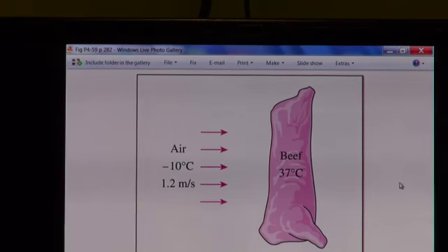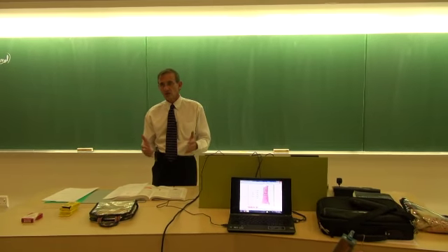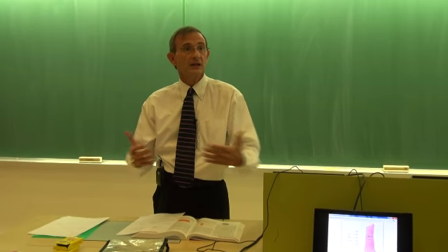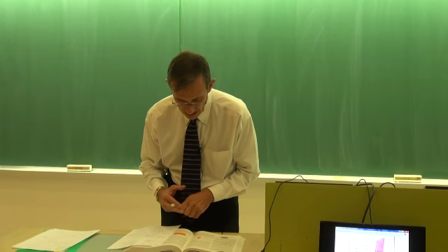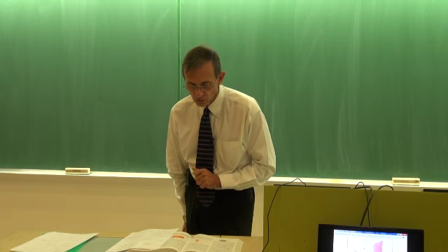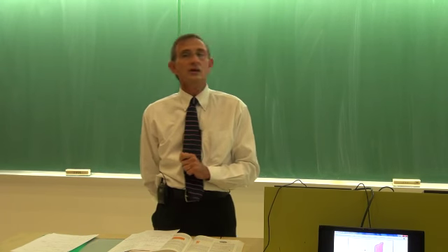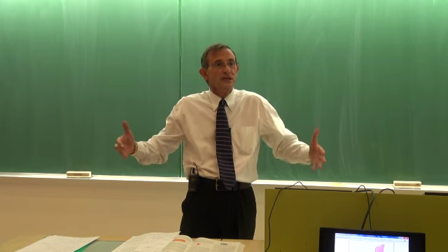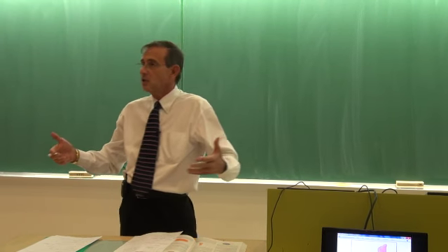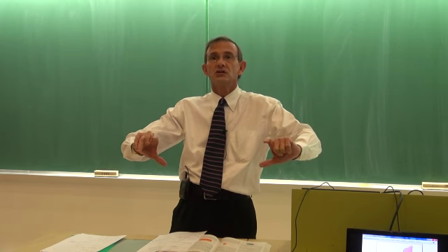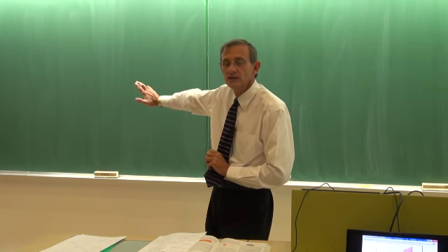Okay. Normally in these types of processes it is very important to cool the carcass down, but not to freeze it. Okay, so they wanted typically a temperature of 4 degrees Celsius, but then they also ask, also determine if any part of the carcass will freeze during the process. Okay. So will there be somewhere, some of the meat, will the temperature drop to 0 or lower than 0? And then I'm going to add a few more sections. You don't have to write it down now, I'm going to do it in detail.